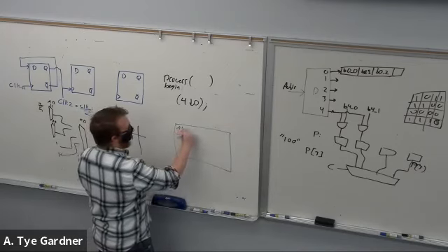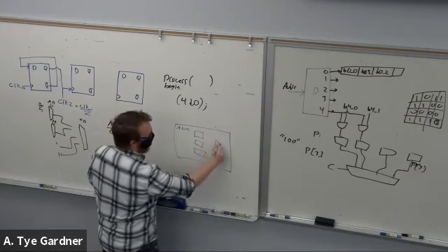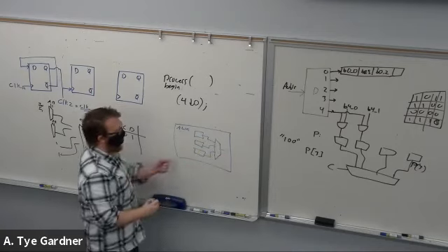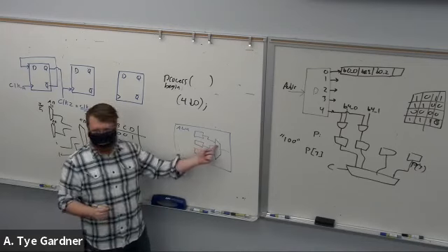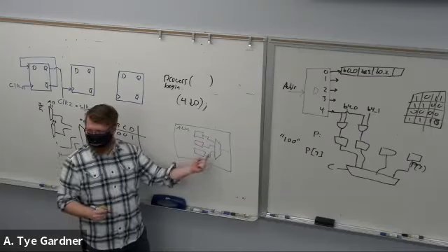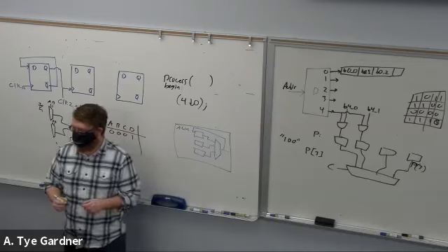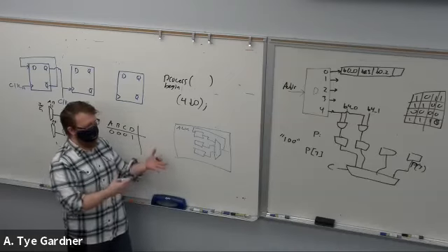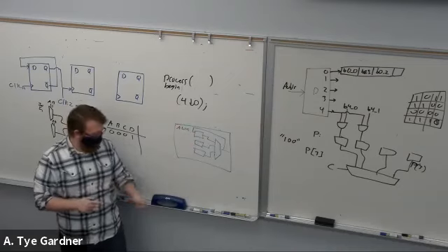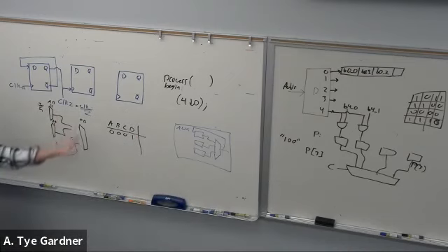So, right, you guys have this ALU and you have these blocks. And then you would just want to make sure things like, does this output actually connect to this input, or did I mislabel the signals? Do they have the wrong size of vectors? Maybe there's feedback around or something if I drew it in the diagram, that kind of thing. Just ask, did my code realize the diagram? Which hopefully should be easy if you've done the project, right? So that was the point of the project, is to understand hierarchical design.